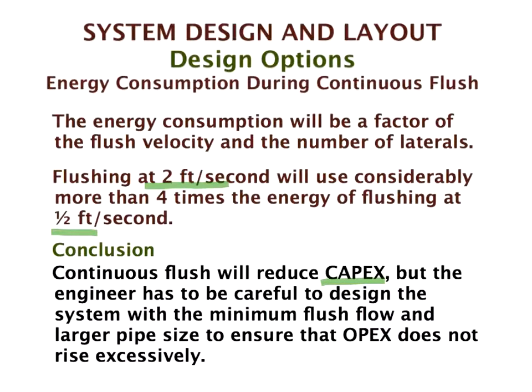The engineer has to be careful to do the design with a minimum flush flow and large pipe sizes to ensure that the operating expense does not rise excessively, to see that the trade-off isn't excessive. And again, if he's careful and does it right, it works. I'm not for one moment saying it won't work. It does work, and it's a trade-off that should be carefully considered by the engineer.